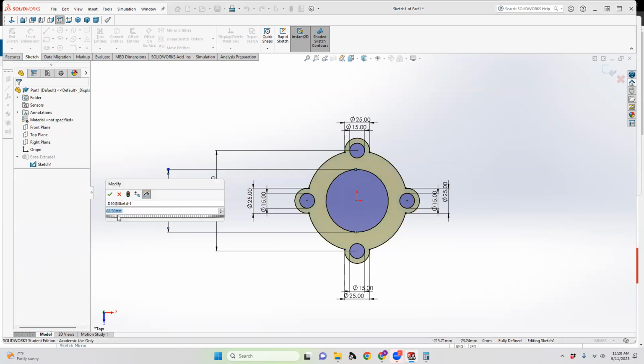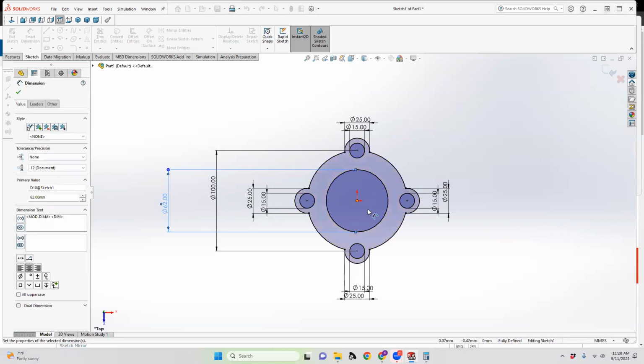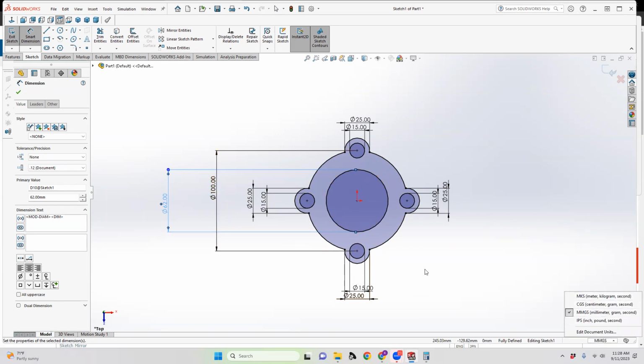If you're trying to include tolerance in something and say 50 millimeters plus 2, meaning 1 millimeter clearance on either side. You could do even this case, 60 millimeter plus 2 millimeter. So 1 millimeter clearance all around. And this would give you your 62. So you can kind of enter formulas. You just want to be mindful of, again, what unit system you're in.